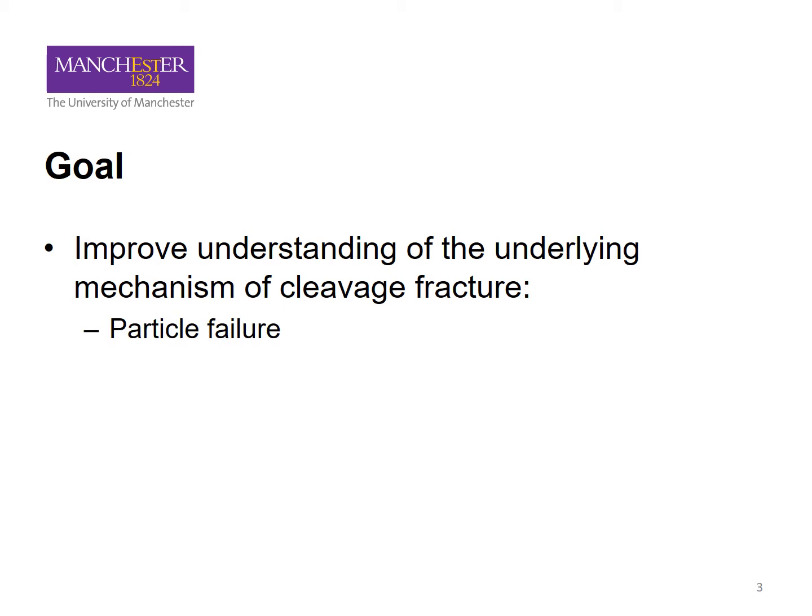First, a particle fails. The particles are generally considered to be elastic brittle particles, typically carbides, and as the surrounding matrix plastically deforms, these particles fail due to plastic overload. And failure is generally assumed to be the particle cracks into 2, leaving a sharp crack. Then microcracks nucleate from this point.